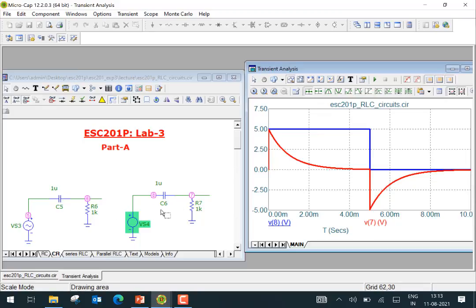So, like the previous circuit, where the RC circuit is more like an integrator, this circuit is more like a differentiator. Not a perfect differentiator, but you are seeing that when you apply a pulse, it's like differentiating this particular voltage here, right? And the differentiation would become even better. You would get a very sharp pulse if we make the time constants very small here.